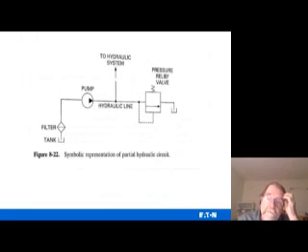And then this is how the circuit looks. You have your filter and your tank on the left there. There's your pump. And then up top you go to your hydraulic system, to your direction control valve. And this is your pressure relief valve. If there's too much pressure up here, it builds up in this system. So this pump is producing the flow, but it's getting a lot of resistance to flow. Guess what it creates? It creates pressure. Resistance to flow. And once that resistance gets up to like 500 psi, then it starts diverting the flow from the pump back to the tank instead of up here. That's how a pressure relief valve works.